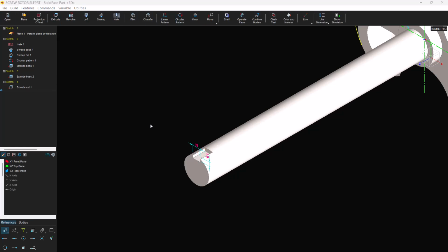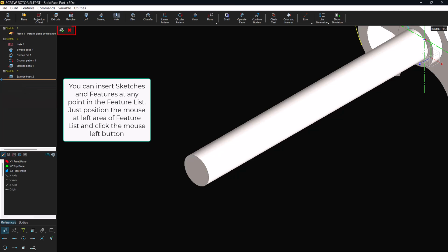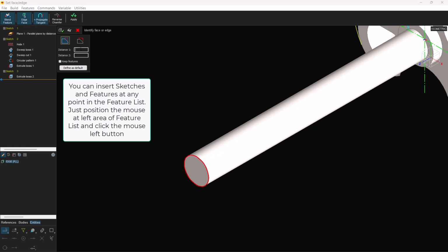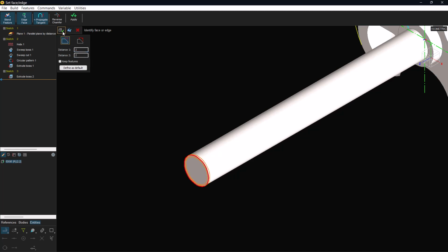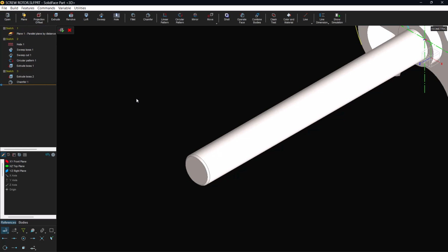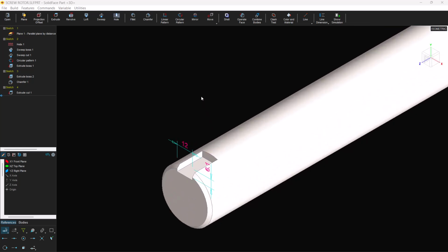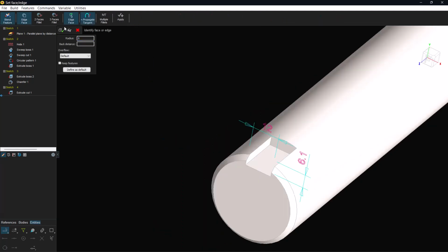I forgot to create the chamfer before this last feature. We can open a constructive insertion point before it. Creating an insertion mode. Create chamfer with values of 2. Close the insertion. Make fillets of 6 on the inner edges.